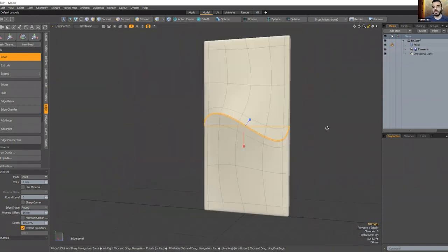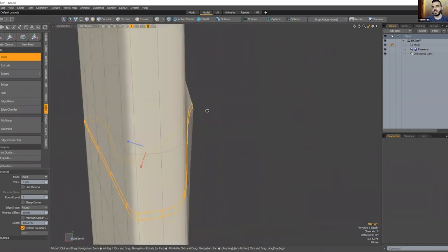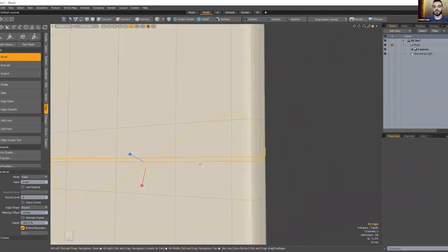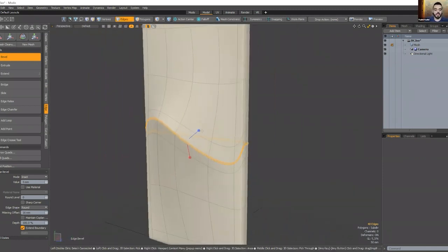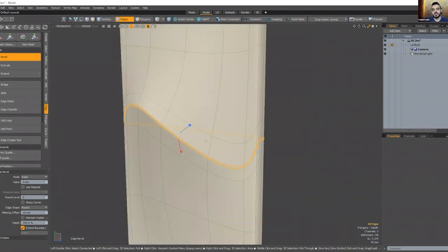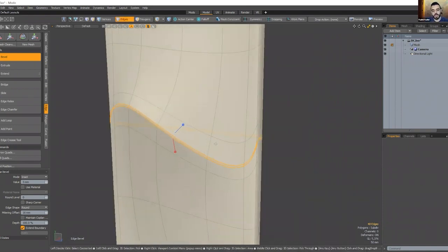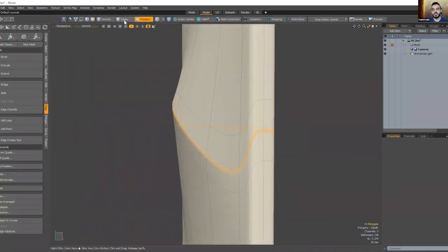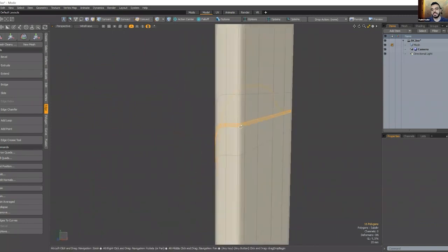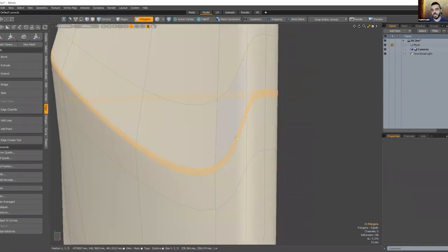I think I want to cut it through here. I do like the fact that there is a little bit of a crease that's happening in the system. So that's the first thing. I'm adding a joint to this. And the way I'm going to do this, as it's selected, I'm going to hit Alt-3. And what that does is basically switches me from edges mode to polygon mode. Instead of having to choose the edges of the geometry that I was working with, that selects the polygons that are in between.